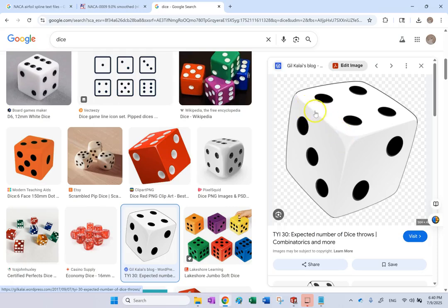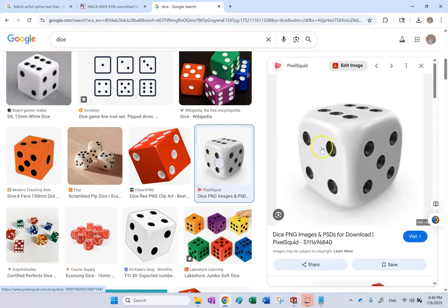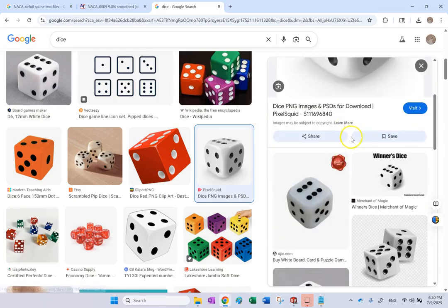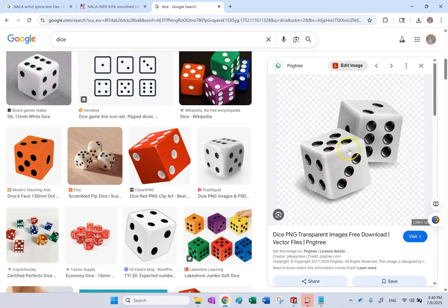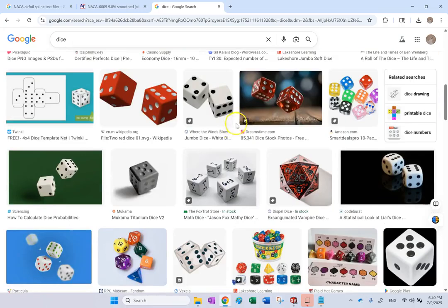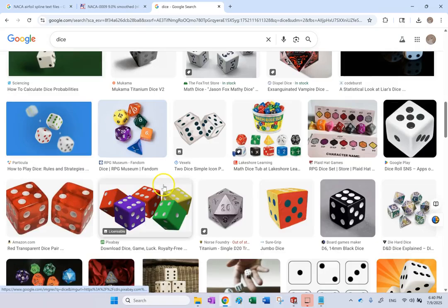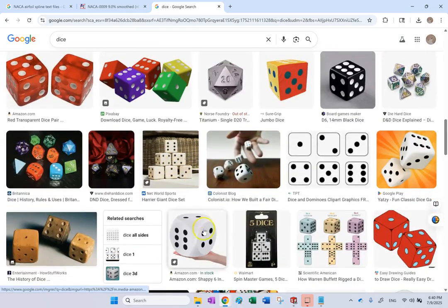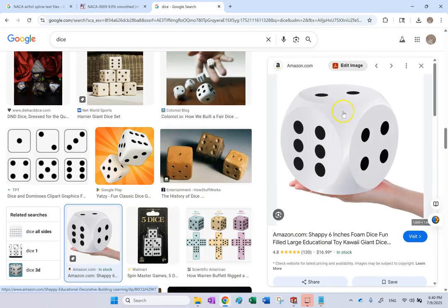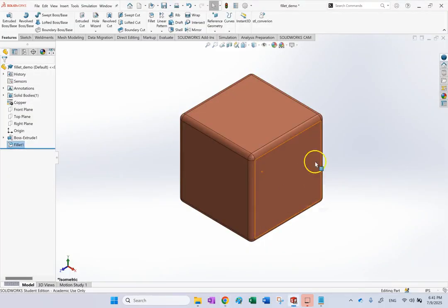So the fillet radius is quite small in the middle, and as you get closer to the corner, the fillet radius gets a little bit bigger. Of course, again, we have some simple ones like this, but these are CAD models. In reality, as I said, most of the time you see that a radius is kind of like this. So can you make a fillet like that, that is bigger toward the end? For that, you might say, well, I use a variable fillet radius. You know that you can use a variable radius fillet if you want.